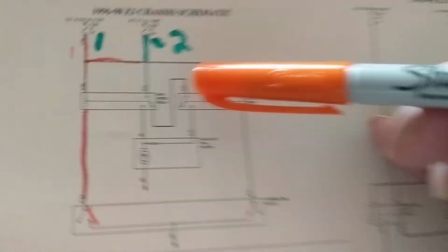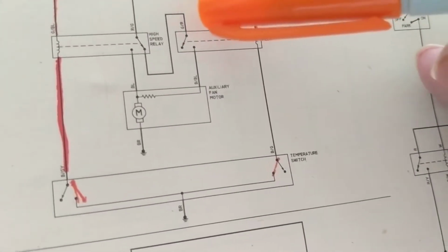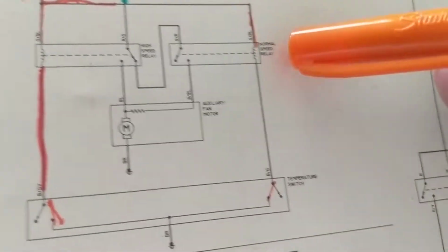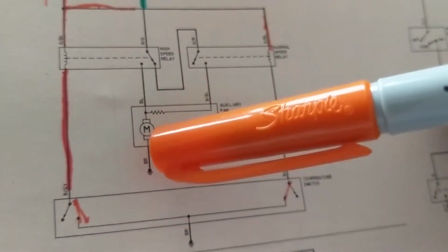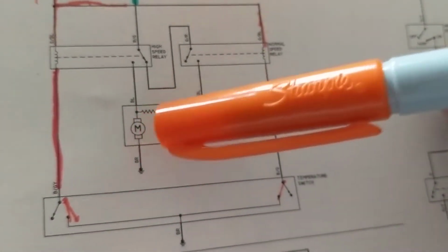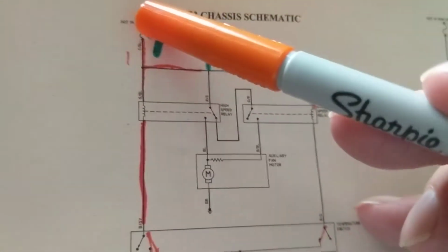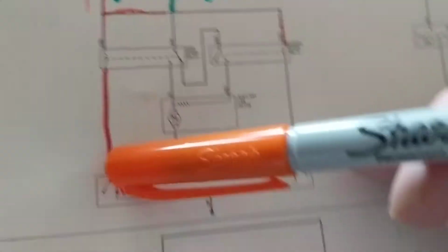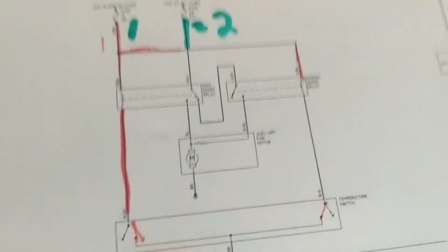Again, high speed relay, I expect not to have a resistor when it's in high speed. When it's in normal speed, I expect to have a resistor to limit the speed of the fan. So let's go this way. Current flows, the starting point is from this one here. Now, the question you have is which position will the switch be in, right?